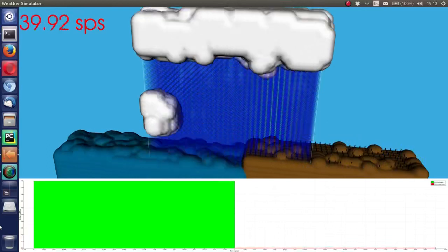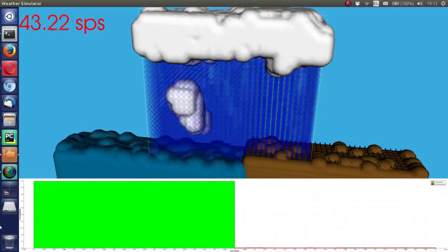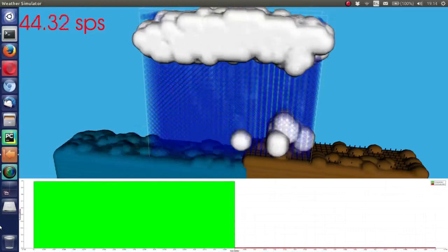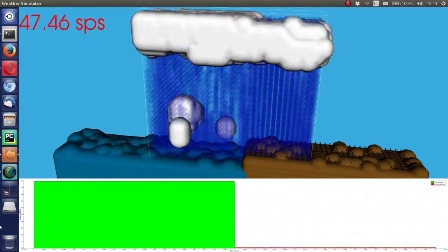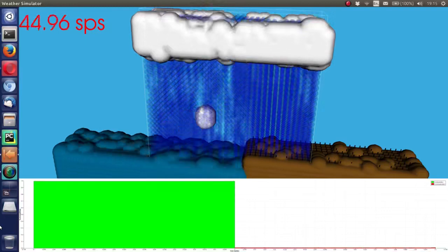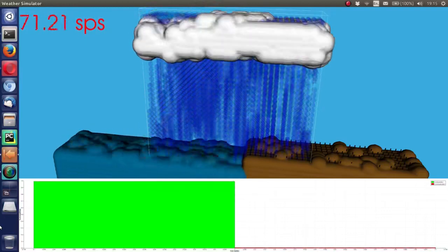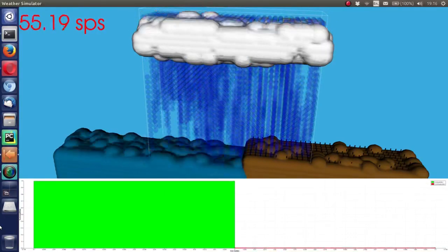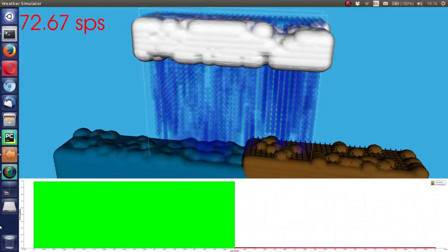So for this simulation, only one core is used, and hence the time spent on computation is much greater than the time spent on communication. Whereas if more cores are used, the code will spend more time on communicating between each core than computation. Therefore, we want to spend as little time as possible communicating while increasing the performance. The optimal decomposition strategy has to be used.